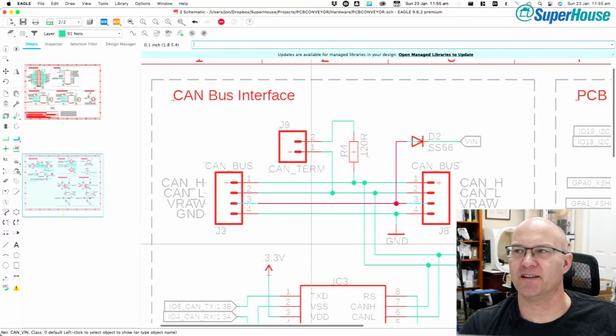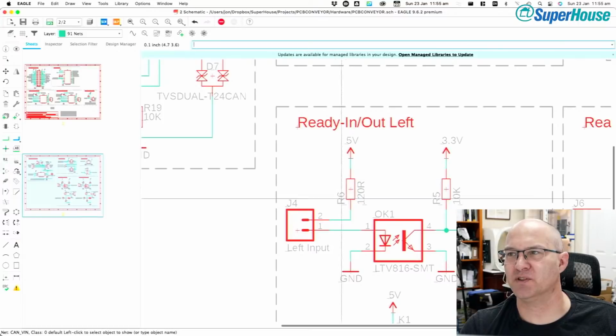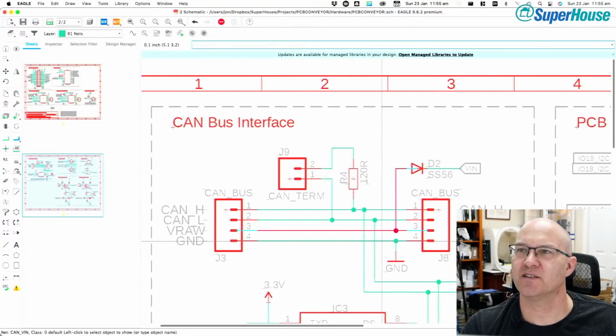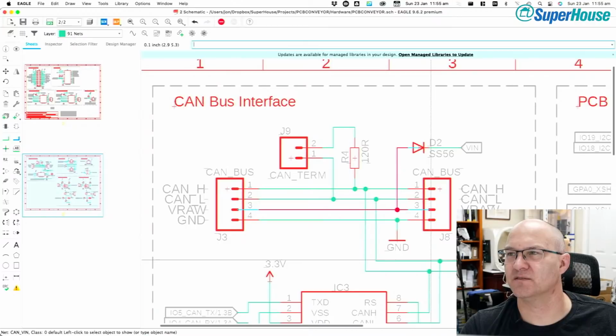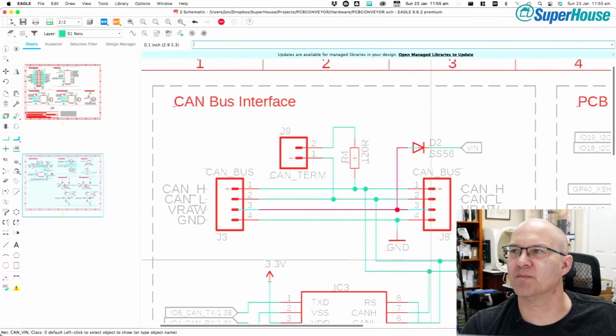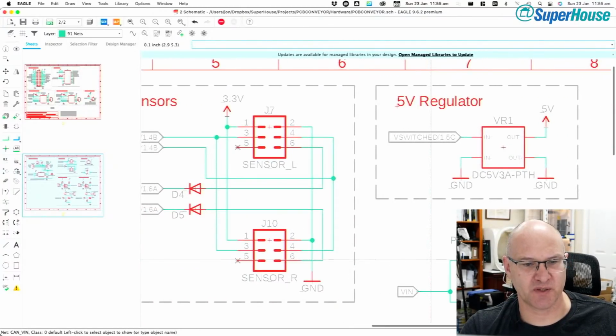Yeah, maybe that'll be okay. There's probably enough latitude that if I just set the resistor on here to suit a 24 volt rail, then it should still work at 12 volts as well. The LED should illuminate enough that it reaches the threshold and turns on. So yeah, I think you might be right, Johnny, that maybe I should feed this, and someone else suggested it as well. Jordan suggested run it from your 24 volt rail. Yeah.